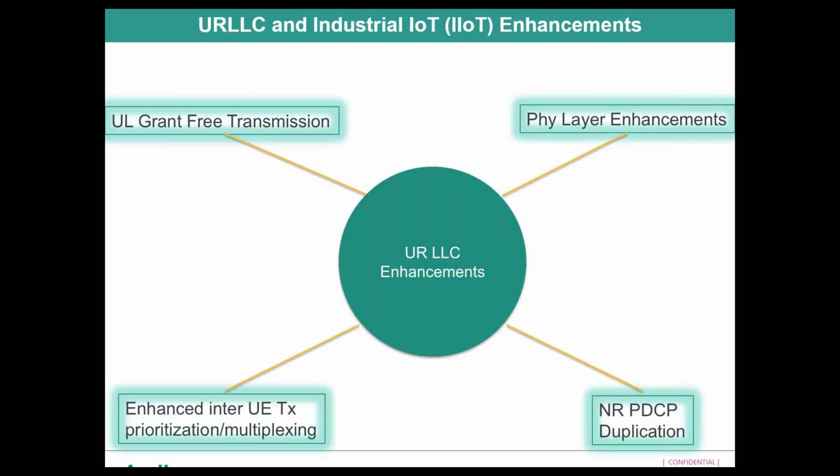So some of the items that are going to be helping us with URLLC, as I said, are lower latency through supporting the different subcarrier spacing and shorter transmission time intervals. We have what we call mini slots, whereby you don't have to use all the 14 OFDM symbols, but you can group and transmit a series of fewer than 14 OFDM symbols, right? And then you can also do PDCCH monitoring, and something we call PDCP duplication, right? So there is going to be enhancement there, as we talked about different enhancements over here.